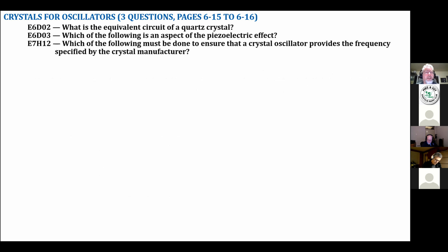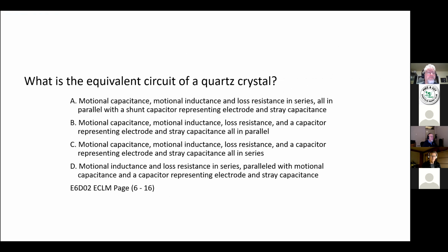Crystals for oscillators, three questions. What is the equivalent circuit of a quartz crystal? A, motional capacitance, motional inductance, and a loss resistance in series, all in parallel with a shunt capacitor representing electrode and stray capacitance.